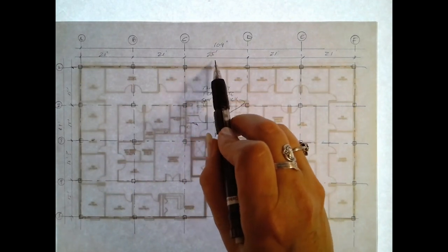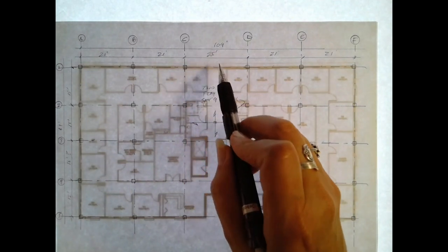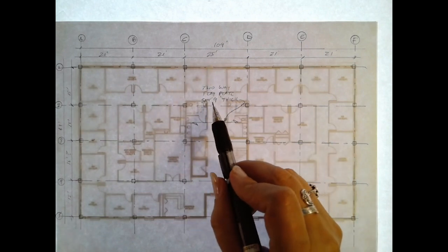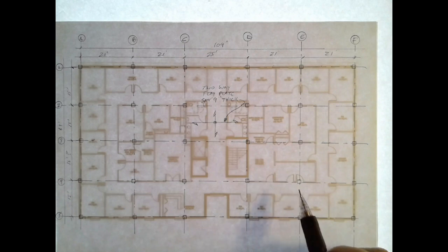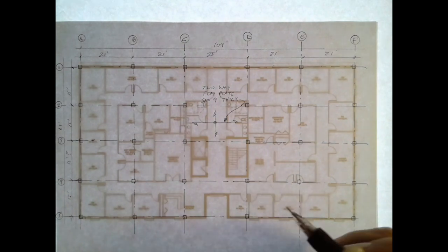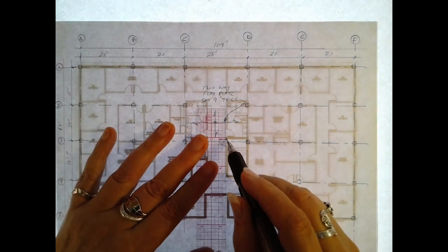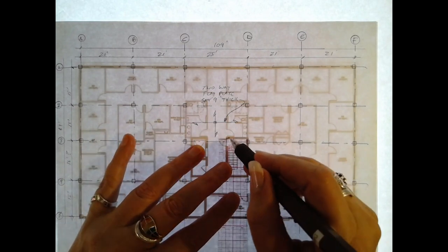The 25-foot span, that is the outlier on this. So I'm kind of rounding down a little bit and saying that 9 inches, which works for a 21-foot slab. Now there's a couple of things that, just FYI, I don't make a part of a student exercise, but we do have penetrations here, right? There's a stairway right here.